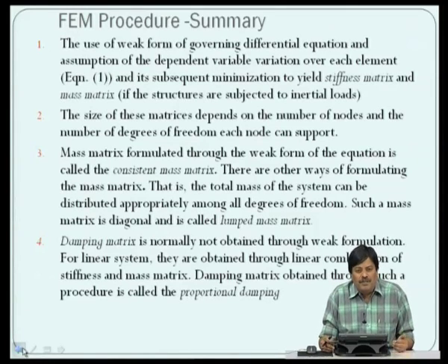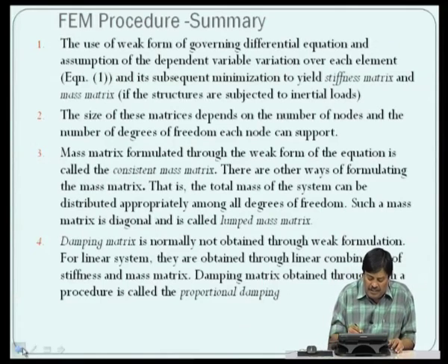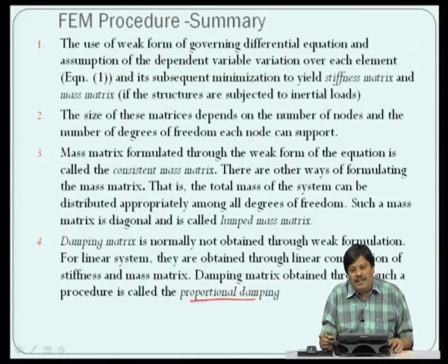But however, to represent it, they formulate the stiffness and mass matrix and take the damping matrix as a combination of the stiffness and mass matrix, and such a matrix is called the proportional damping matrix.